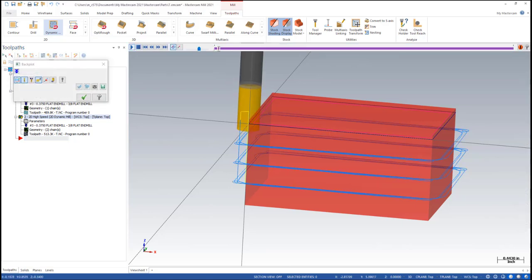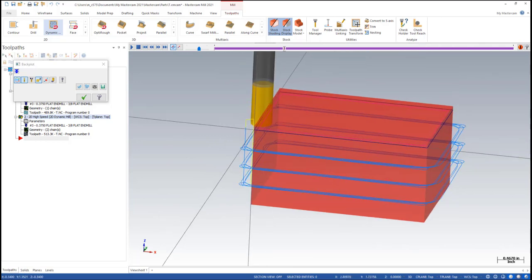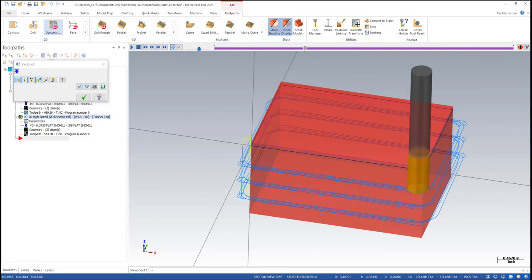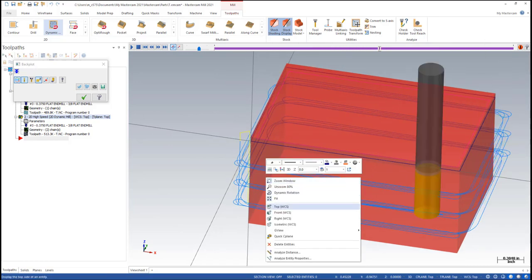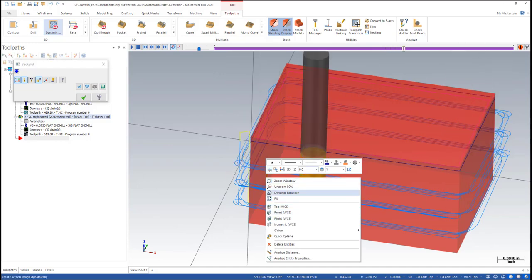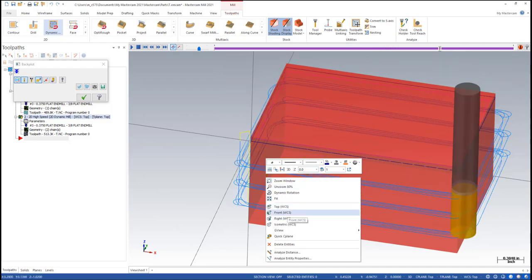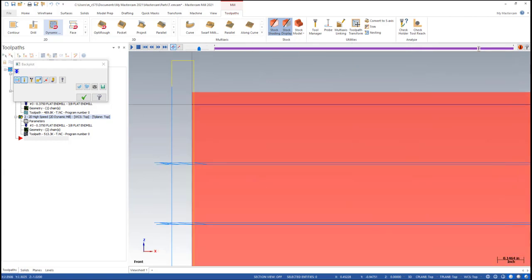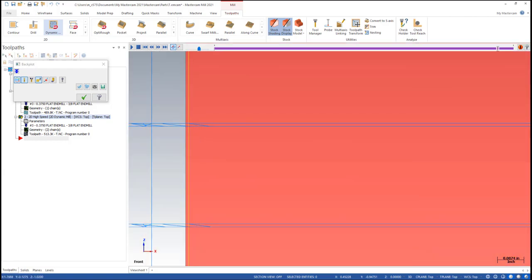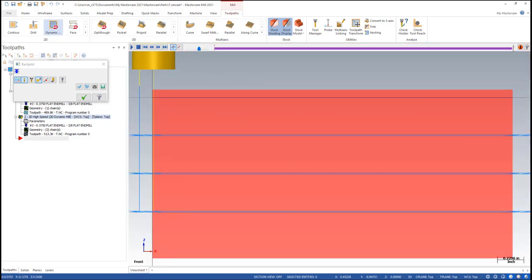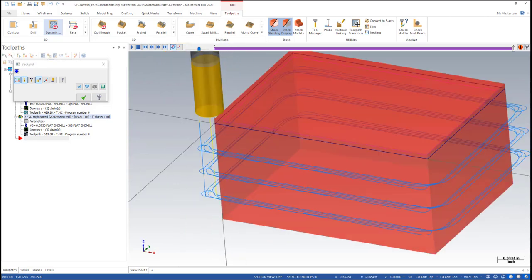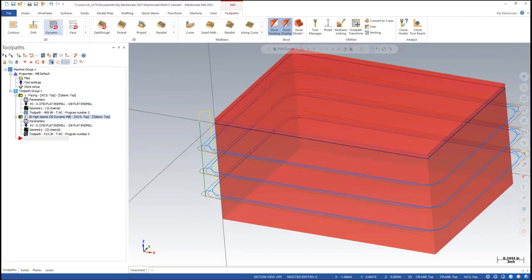And if we want to back plot it, we can. Just let it run. It just gives you an idea of what it's going to look like. And these little loopy moves like that right there where it comes back, those are those micro lifts where it picks the tool up just a little bit and it doesn't rapid, it moves at a feed rate, but it's a really fast feed rate. So if you look, you can see the micro lifts where it picks up and then moves. And then this lower level is our actual commanded cut depth. So that looks good. You can green check that.